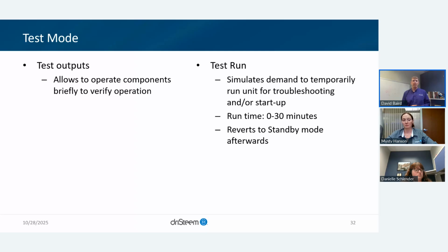Basically, this simulates demand for a period of time. After it's done, it's going to move back to standby mode. I mentioned earlier, standby mode means it's going to sit there idle until it's enabled in auto mode. So something to keep in mind: if you use that test run, flip it back to auto later, so that way it's allowed to run when it needs to.